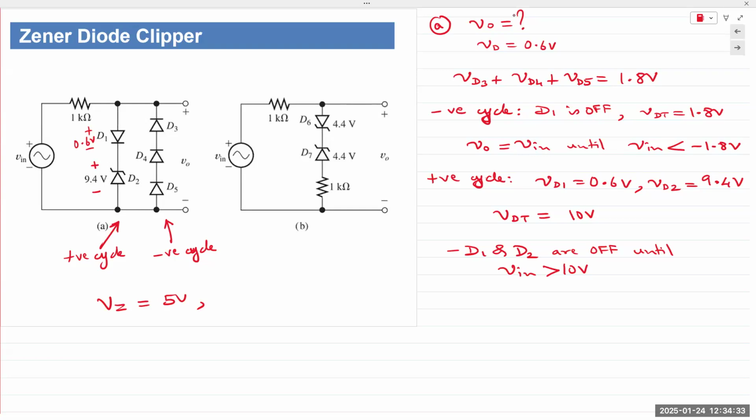And then once you analyze the circuit based on that, we can go in and use a different model to determine our exact voltages and currents. Even with just using an ideal diode model, where we neglect the effect of the 0.6 volt diode voltage drop, the results are surprisingly accurate.